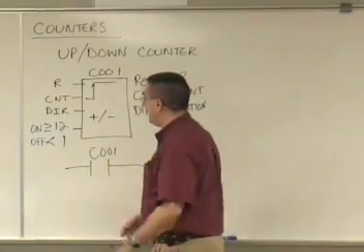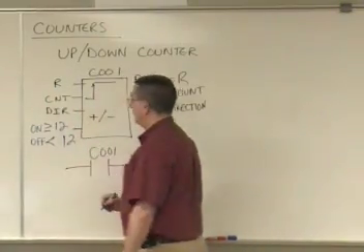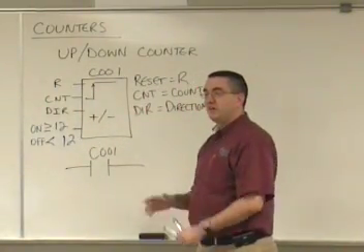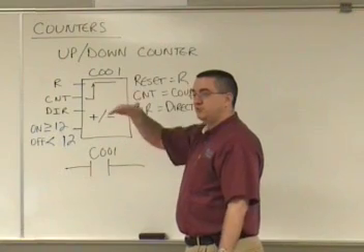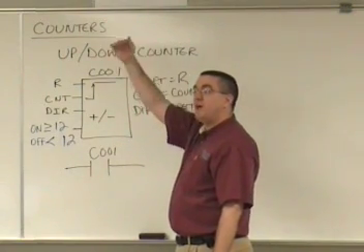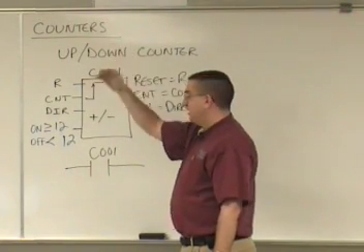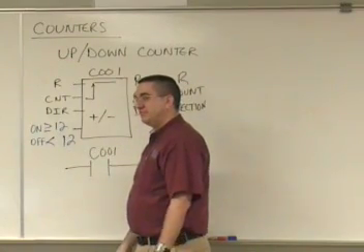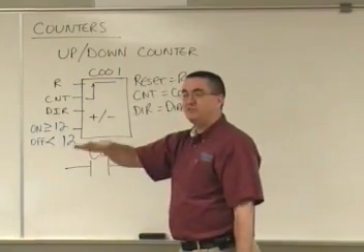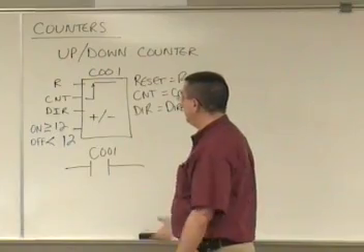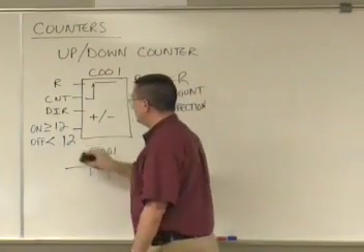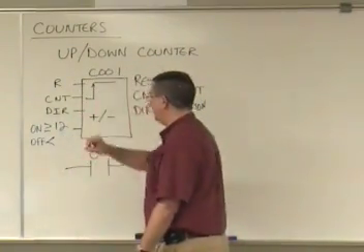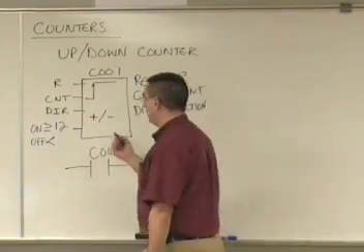Now it could be that you have 12 in there. If I had 12 in there, and I'm going in the upward direction, 1, 2, 3, 4, 5, 6, 7, 8, 9, 10, 11, 12, it would turn on. And then when would it turn off? Anytime I got to 11 or below, right? So anytime I was less than 12. Just to give you a little bit of an idea, I'll show you a little step diagram over here, how it's going to work.